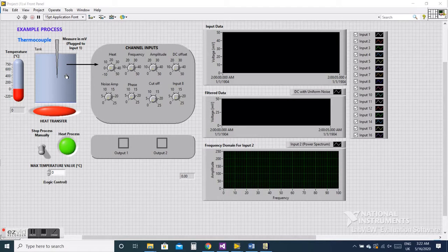To transduce the measured voltage to temperature, it was necessary to search for real thermocouples catalog and take some voltage temperature pairs to obtain the equation that fits that behavior. This equation would be used to approximate the temperature the fluid has according to the voltage the user is sending.